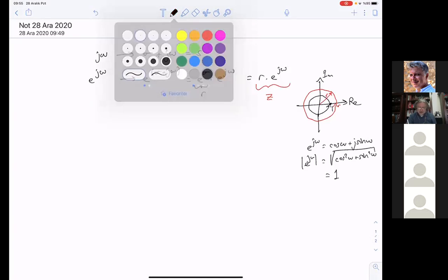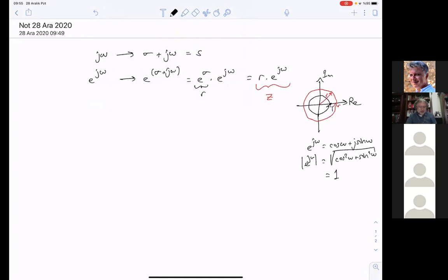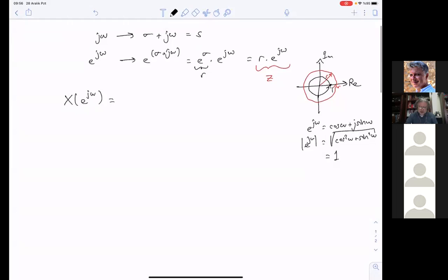But what is the Z transform? The Z transform is actually like this. You may remember the discrete time Fourier transform. What was it? The discrete time Fourier transform, let's remember that one, that it's critical, was already equal to a summation n from minus infinity to infinity, x of n times e to the minus j omega n. You remember this? It's the discrete time Fourier transform.